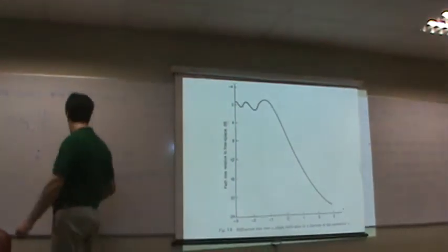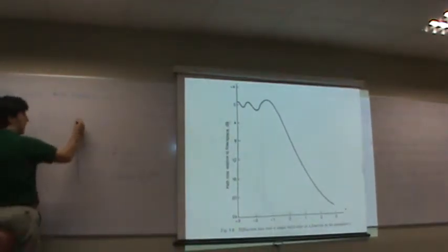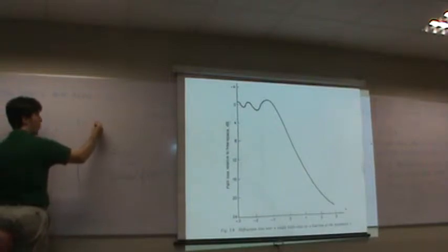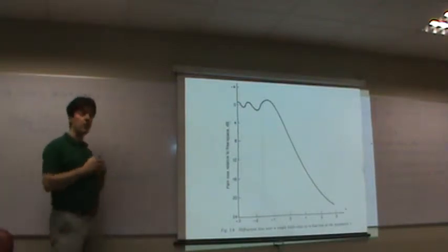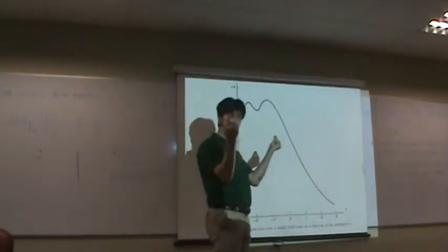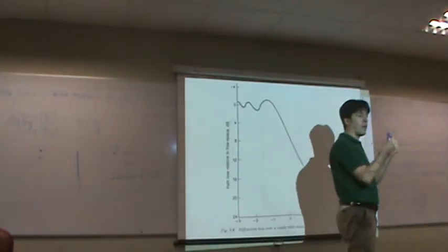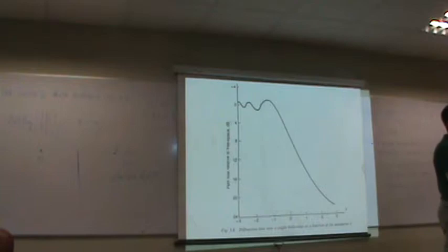In this situation, the electric field that you are receiving is 1/2 of the field that you would receive in free space, even if there is a direct visibility, geometrical visibility between A and B. You lose 6 dB.